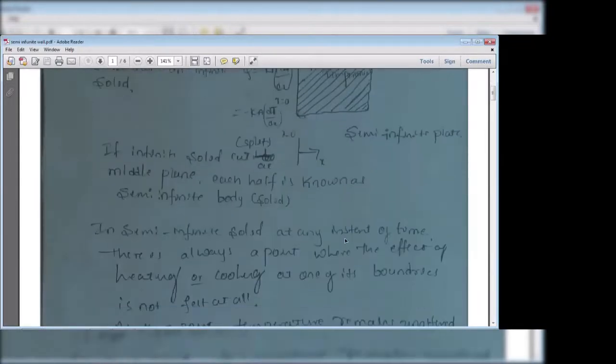Because of this, we have the semi-infinite plate here. If the length is large, in the case of a pin or any other material, sometimes the temperature at the boundary is also equal to the temperature of the surroundings. We discussed this in the long pin case also.